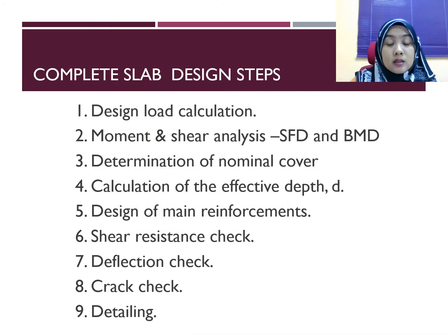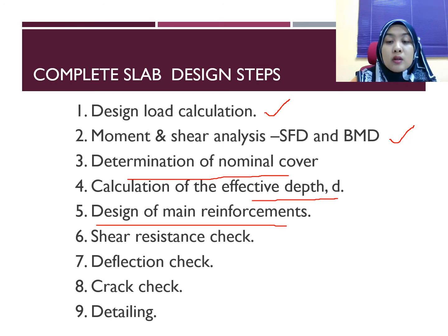Okay, and then we follow the design steps. First you need to do your design load calculation, and then you draw your SFD and BMD based on the values that you get from the table. Then you can determine your nominal cover and effective depth value. Then you can design your main reinforcement. For main reinforcement, you have two values, which is for the Msx value and also for the Msy value.